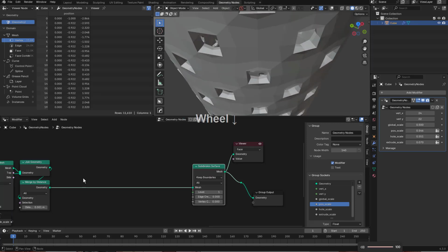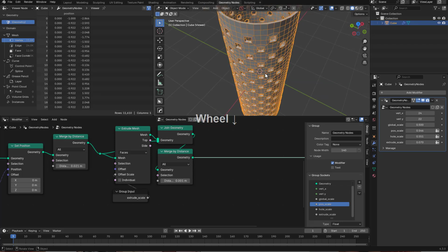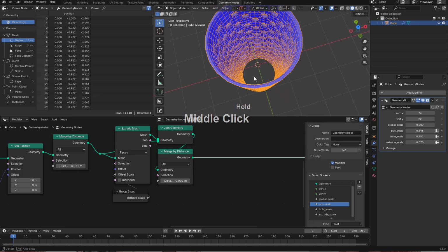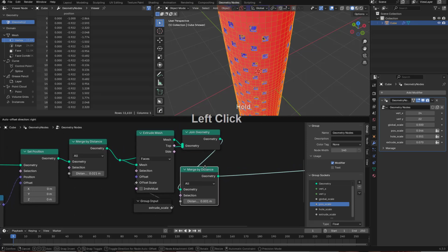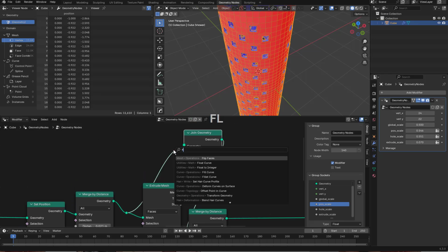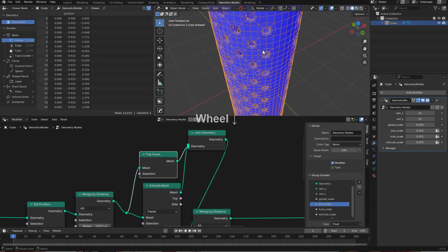subdivision, which our subdivision for some reason did not work out. Now, why did it not work out? Well, this is where you want to put your diagnostics hat on, because if we go into face orientation, we could see that the second face just did not get its normals flipped, because its normals aren't going to be flipped like that. So let's do a flip faces, and now we have it behaving the way it's supposed to.